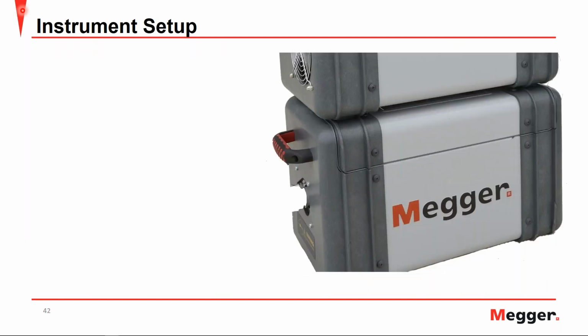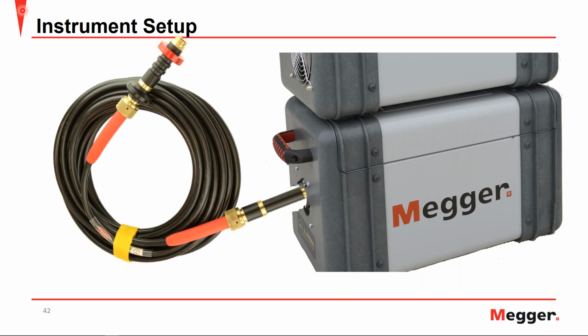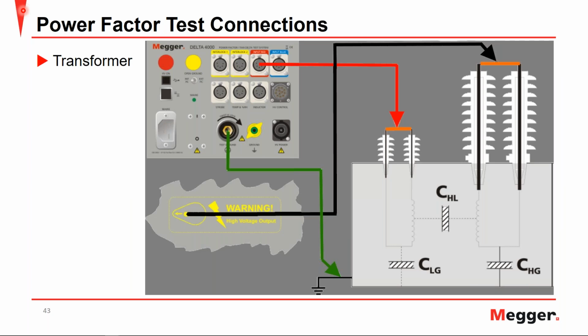Next, let's take a step and look at the Delta 4000, where the control unit is on top and the high voltage unit is on bottom. Here we have the high voltage cable, which is simply inserted and slid into the high voltage unit and locked into place via a locking mechanism. It's just a pull and release. The high voltage cable has many different terminations depending on your application that can range from a hook, variable Kelvin clamp, as well as small clamps for bushing adapters.